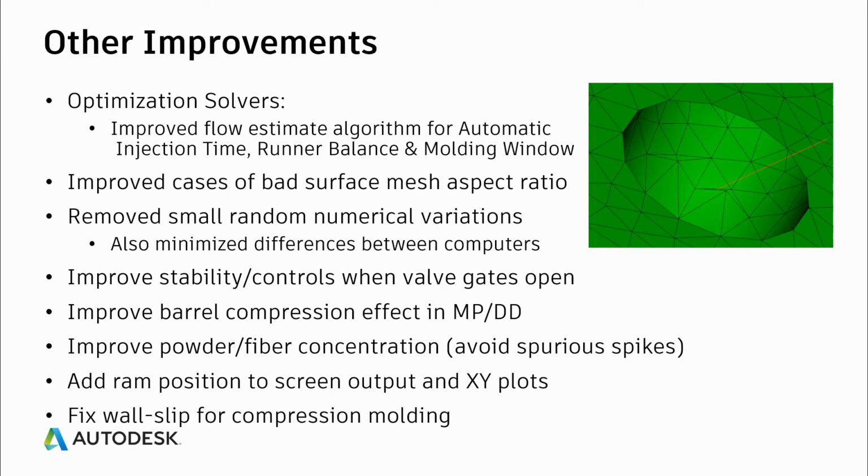There have been some significant improvements to the stability and time step control of analyses where valve gates are included, particularly at the time when the valve gates open, and there can be quite an almost explosive flow rate and very high shear rates, and we need to control the analysis at that point with very fine small time steps to capture those effects. There have been improvements to the calculation of barrel compression effects for the midplane and dual domain solver, to more closely agree with actual molding experiments and to more closely agree with what's already been implemented previously in the 3D flow solver.